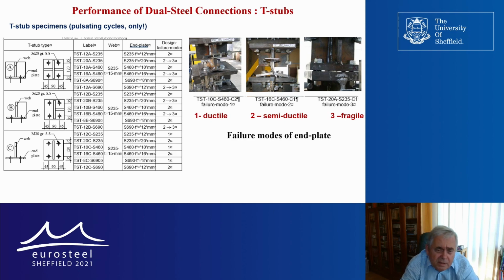As you know, concerning the failure modes of T-stubs which are bolted in the structure, we have three modes. The first one is ductile, the second one is semi-ductile, and the third one is fragile.